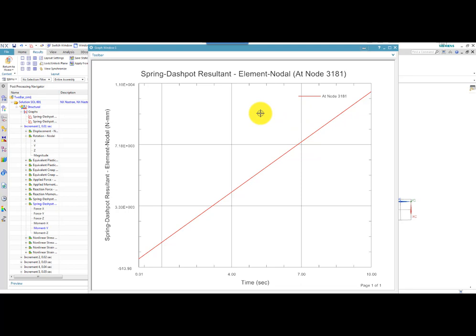You should also note that I have more advanced material, which is demonstrating snap-through and snap-back problems, which has more relation to instability, where I use arc length methods to control the time stepping or the force incrementation and the displacement incrementation when you have limit points and turnaround points. That's more advanced, but these three videos which I created now, the nonlinear materials, the nonlinear contacts, and nonlinear geometry, represent an introduction to different nonlinear finite element analysis effects. I hope you like them.